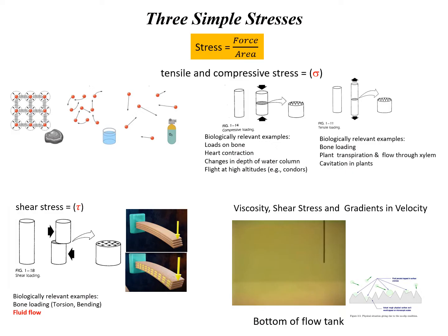So this isn't heavy. It's not sitting on the bottom because it's heavy. It's sitting on the bottom because that layer of water isn't moving. That's called the no-slip boundary condition. So the very first coating is literally stuck to the solid. And then the one above it moves a little bit faster, and the one above that a little bit faster, etc., until you reach the free stream velocity.